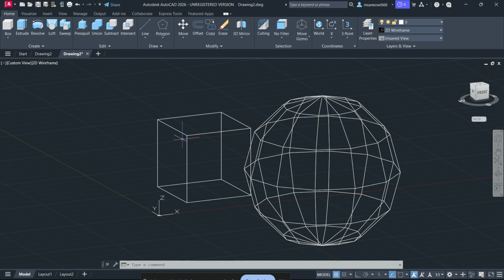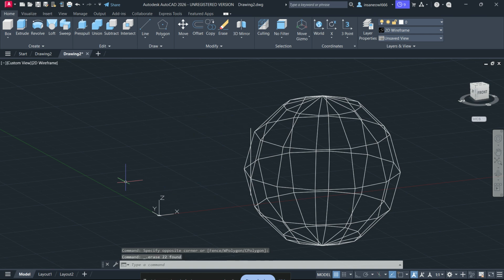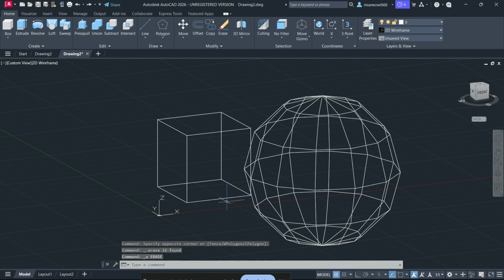Another very effective fix is to simplify the geometry. Complex fillets, tiny chamfers, threads, and detailed curved surfaces can create too much geometric noise for the internal calculation tolerance. If possible, temporarily remove those details and perform the Boolean operation on the simpler blocky version first. Once the main solid has been unioned or cut successfully, you can reapply the fillets or other fine details afterward. This approach is often much more stable and saves a lot of frustration.